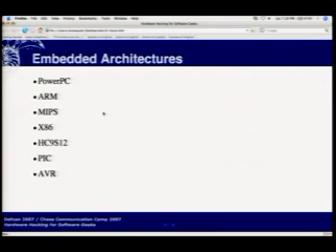The other thing to look at is how many pins the chip has out, because a lot of the PICs will have 16 pins on each side, where 8 of those pins are devoted to VCC, ground, and associated crystal stuff. And then you have 8 address pins and 16 data pins for communicating, just dedicating all your GPIOs to one other device, like off-board memory. And some of those will also dual purpose all those pins, where you can select in the memory mapped registers of the chip whether or not you're going to be using GPIOs in bulk, or like an SPI bus, or any number of other system on a chip type configurations. And they get pretty fancy with what they provide.